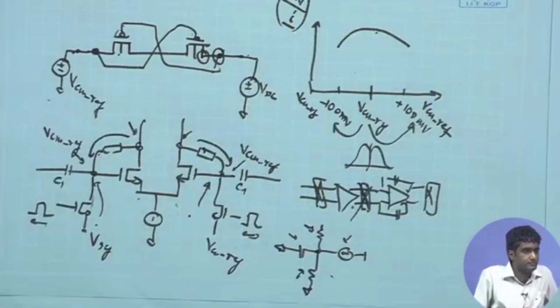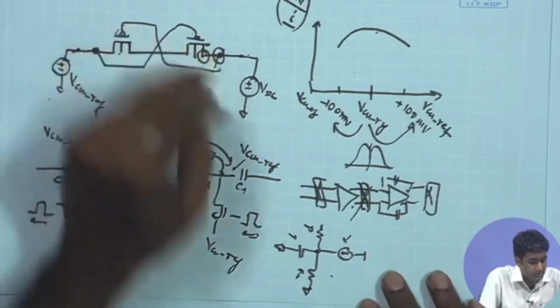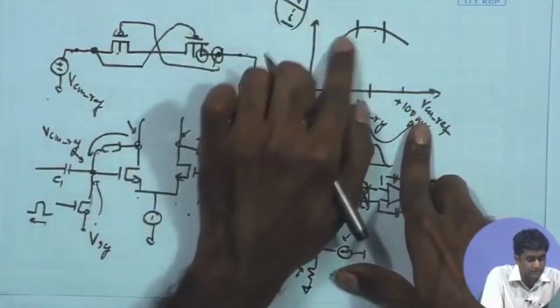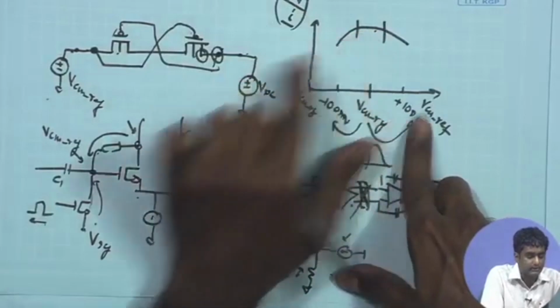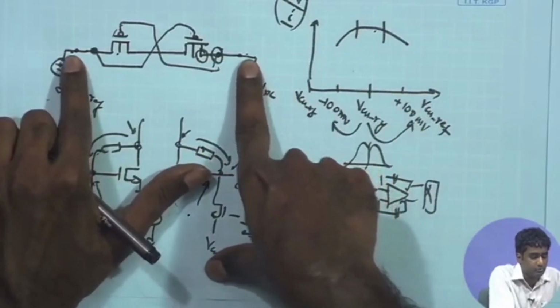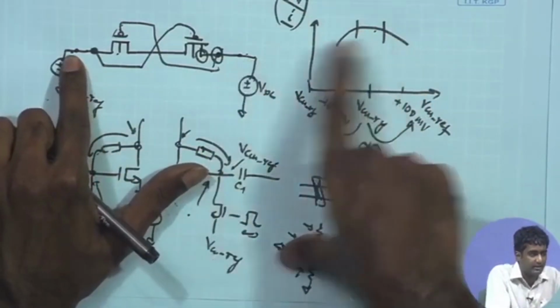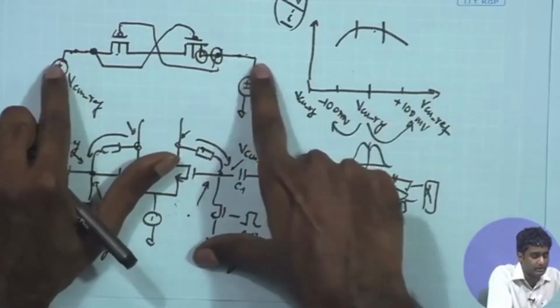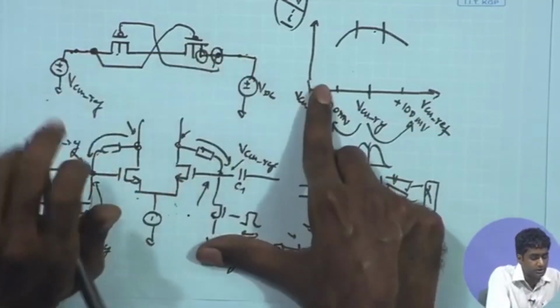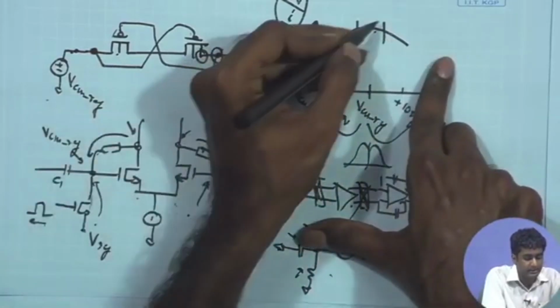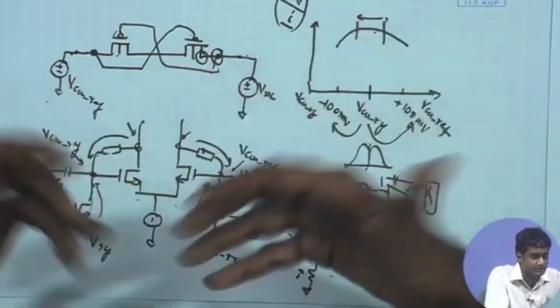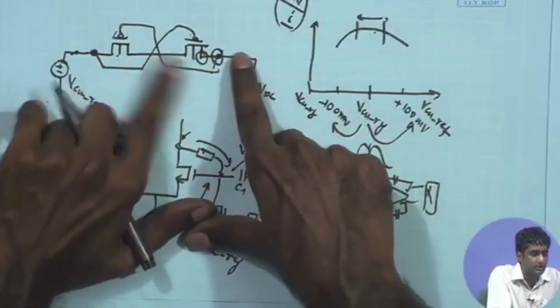So in the calculation of resistance, which current do you have to consider? The best thing to do is look at this, which is valid mainly in the small region. As long as the voltage differential across these two is small, a few tens of millivolts to 100 millivolts, it is valid. After that, this will start dropping because of other leakage currents coming into the picture. So strictly speaking, this is the right region. Beyond that, because leakage starts dominating in other paths, it will not give you a very high resistance.